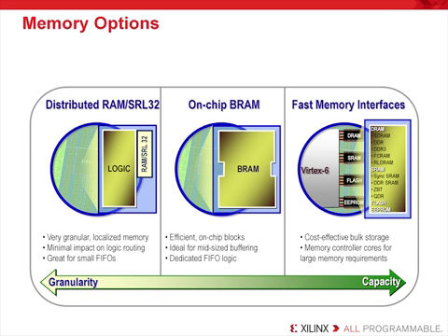Large memory interfaces, or memory controllers, are also supported with Virtex 6. Historically, Xilinx has provided access to soft memory controllers, which are built with Xilinx's primary logic resources, that is, LUTs and registers. These are still supported with the core generator. Virtex 6 now supports even more of the newest memory standards. This is a very cost-effective solution for applications that require a lot of memory space. Construction of memory controllers is supported again by the MIG, and the MIG even optimizes the IOB resources for your chosen memory component.